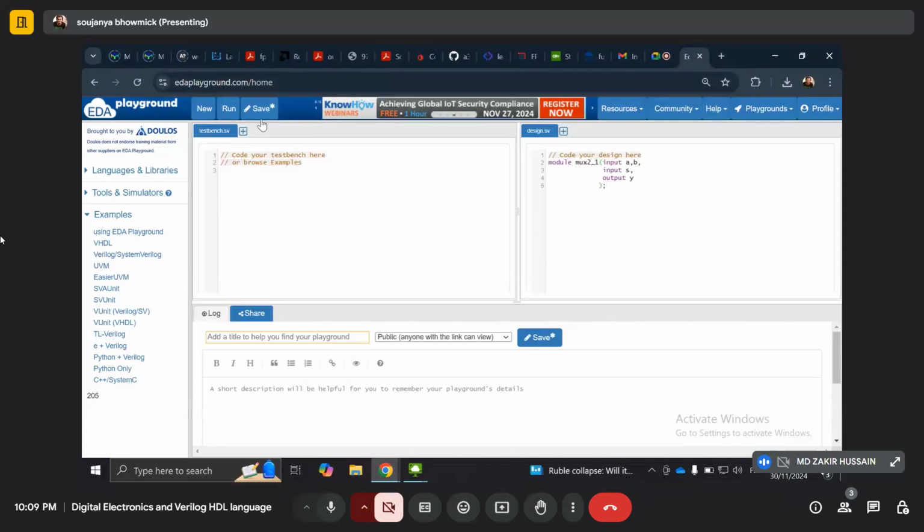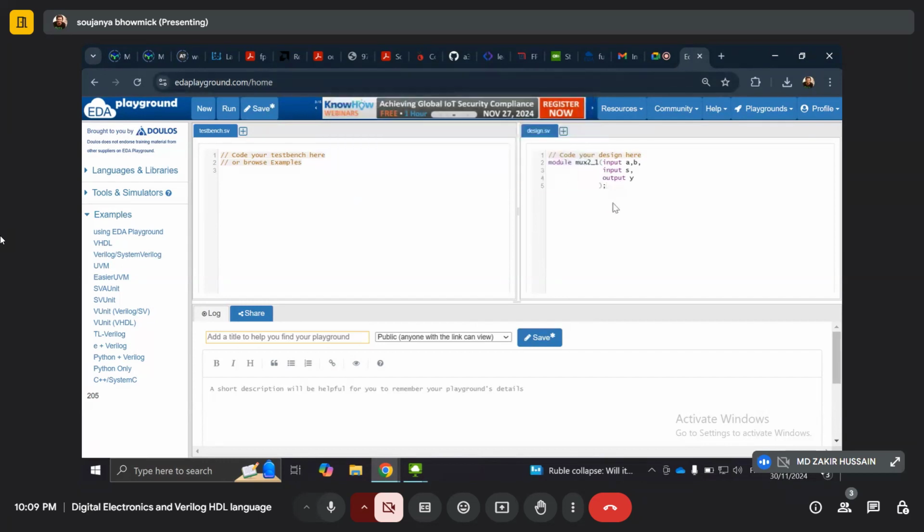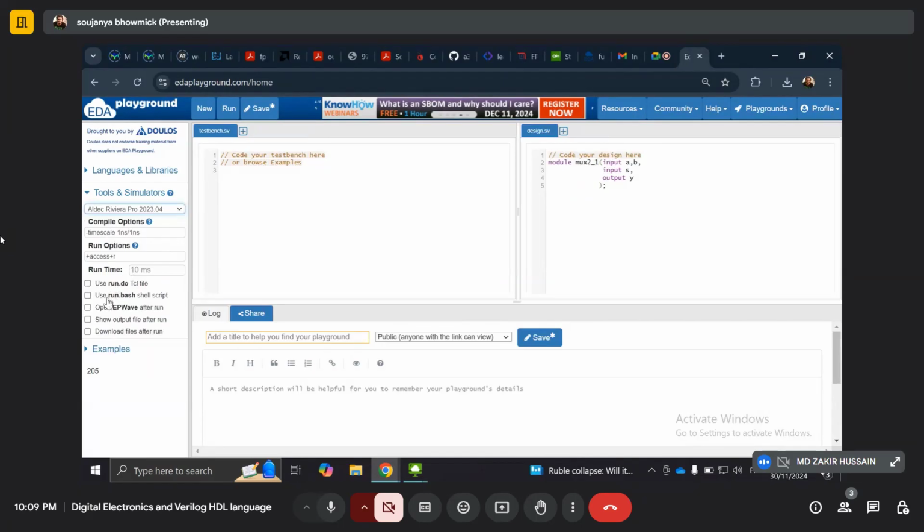The reason for you making use of two inputs there, no, hold on, what is happening? For saving, you have to select the tools. Go to the tools, left, under left tools. Click there. Select, drop down menu, and then Alt. Now you can save, but save it with a proper name. The title is at the bottom. There, mux 2 by 1, using df. Df means data flow.